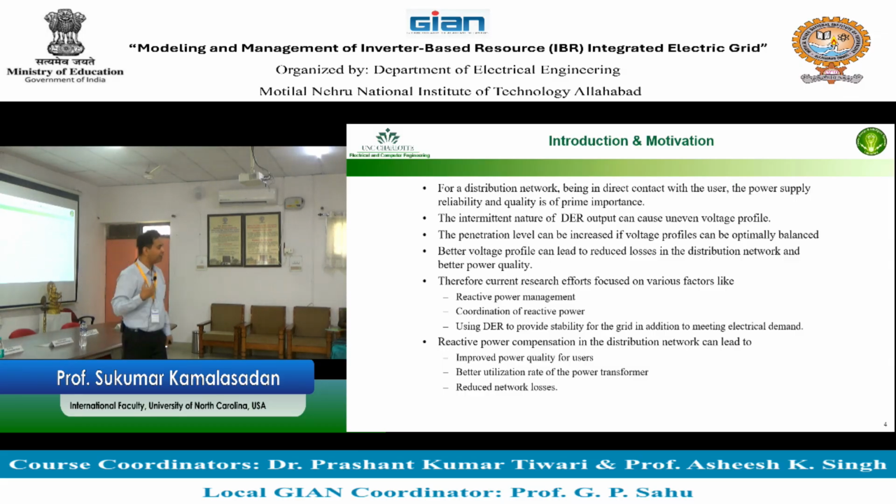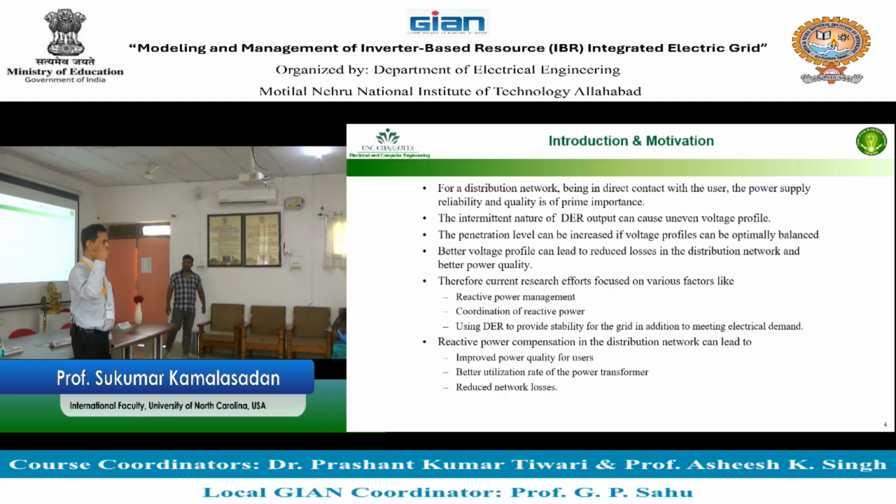However, there is another part which you need to do, a steady state kind of assessment. For example, stability. Remember, we talked about the stability PV curve. That PV curve you probably have to plot with different load variations with respect to time. So there will be multiple PV curves you may have to plot on the stability property for the entire duration, and then go with the conservative, worst PV curve condition. And then you have problems like unbalances, ZIP load, load variation. So these problems are complex, right? There are a lot of things that happen.